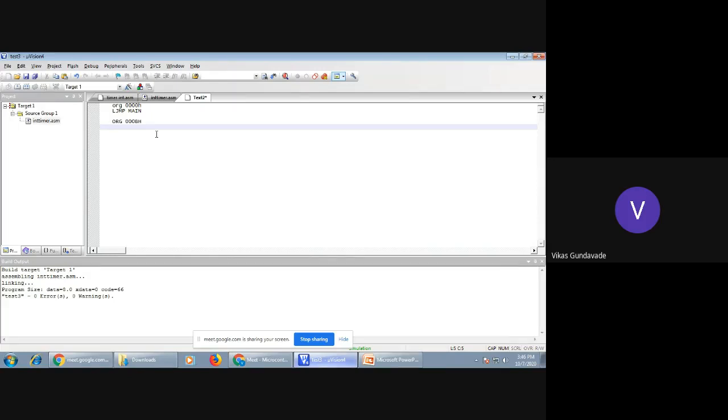That's why we need to initiate that location, and here we will write the ISR as complement of port 1.1. We are only complementing the port pin, and then we will return from the interrupt. Now we will write the program for the timer. So we will start with 0030H.